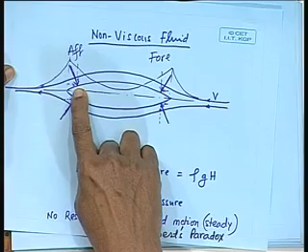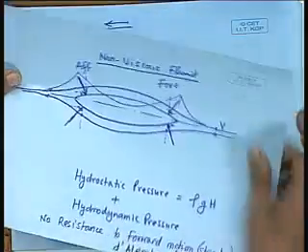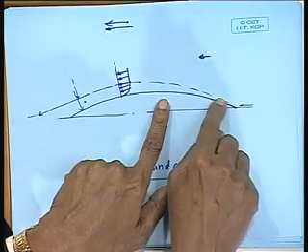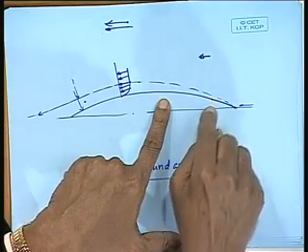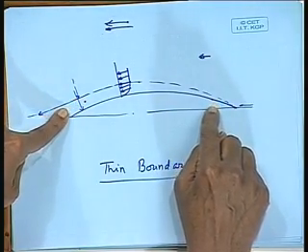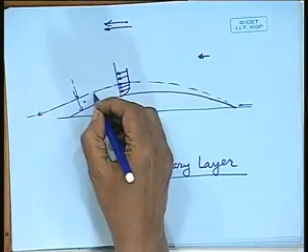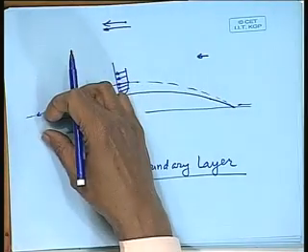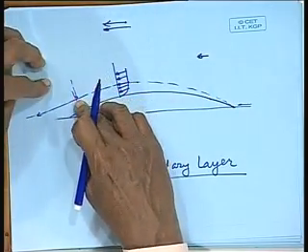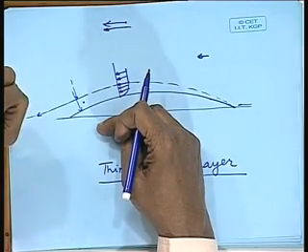You see what we said here. The pressure was acting on the body surface. Now we are saying, from this diagram you can see that the forebody is remaining more or less as it was. So, the pressure forces on the forebody would be as per non-viscous fluid flow, but in the aft body, because of viscosity and development of a boundary layer, the body is smoothed more, not blunted, smoothed more. So, the pressure that is acting on the boundary layer will be now reduced. Do you understand this?